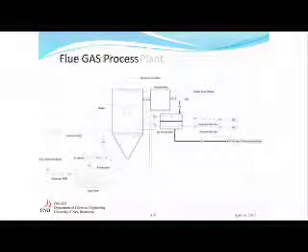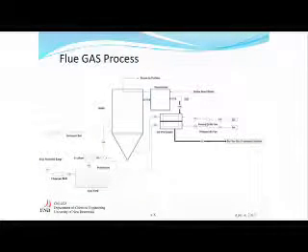And now we will focus on the flue gas generation process. To generate the flue gas, at first coal will be unloaded from the ship and then sent to the coal yard. Based on the power plant's requirement, coal will first be crushed and pulverized and then mixed with air. Coal will be pulverized to as fine as possible in order for efficient combustion, and then it will be sprayed into the furnace of the boiler, where it will be combusted.